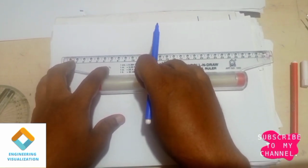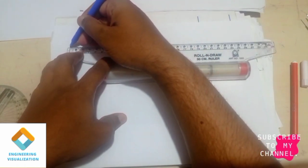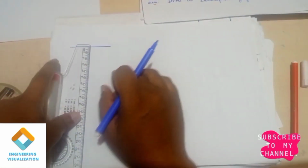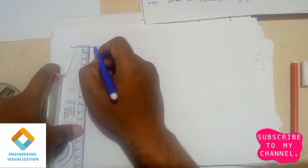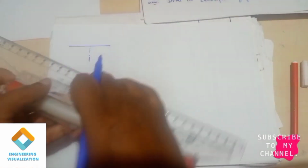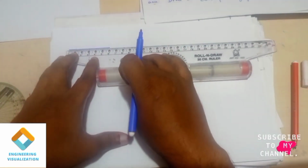Mark a length of 60 mm using the scale. Now vertically downward the height we should consider is 25 mm. From the center of the line I'll draw a vertical straight line downward at a length of 25 mm, that is 2.5 centimeters on the scale. Now from this midpoint, the bottom part we require should be 30 mm.